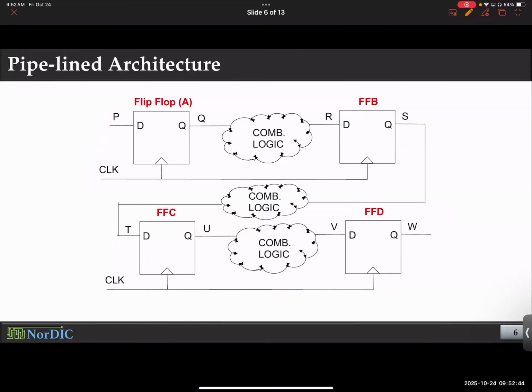So what I'm trying to portray here is that in an actual computing system or an architecture, here is how combinational and sequential circuits work together. So far, did you learn about adders? Okay. What kind of logic is an adder? Is it combinational or sequential logic? Combinational. You don't care about the history. You just care about A, B, and carry in. Done. Right? And then you decide on your output accordingly.